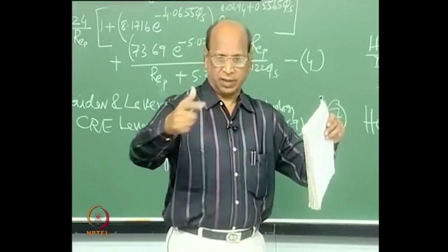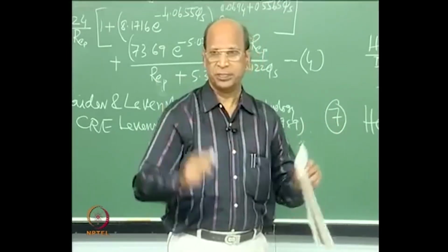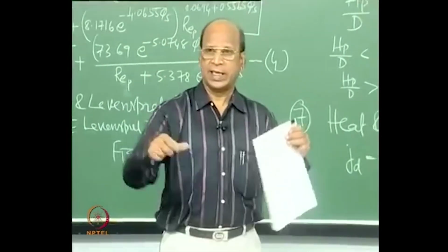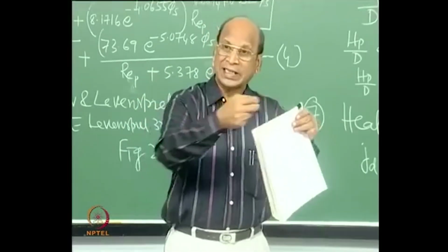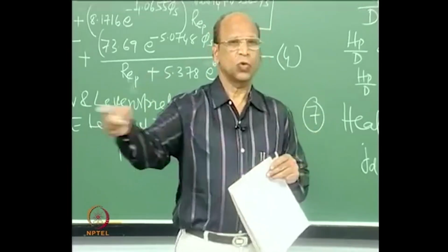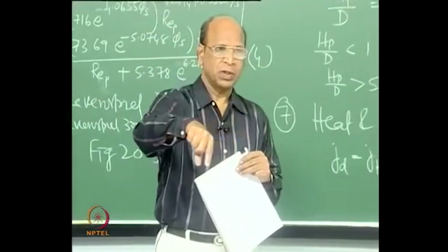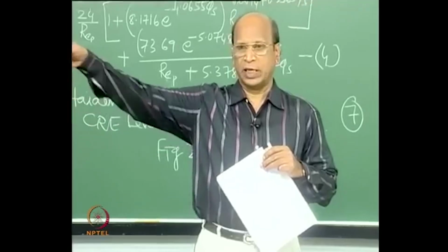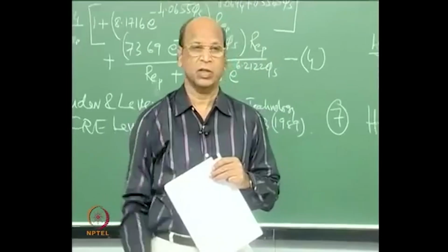Fluidized bed is used as the combustor, where coal is fluidized and burnt. If you go beyond 650 or 700 degrees centigrade, it catches fire if you have sufficient oxygen. Then it burns and you have to extract that heat. To extract that heat, you put cooling coils with water inside. That water becomes steam, the steam goes through steam turbines, the turbine is attached to a generator, and the generator gives us electricity for these lights and all that.